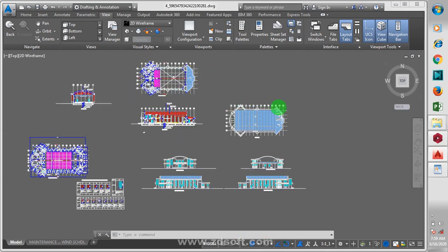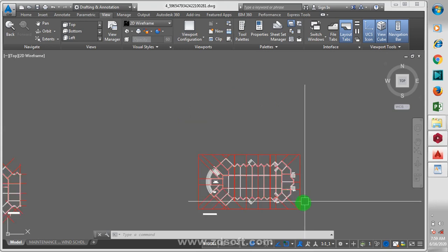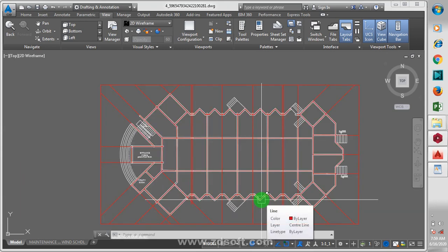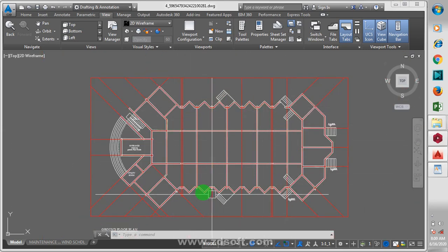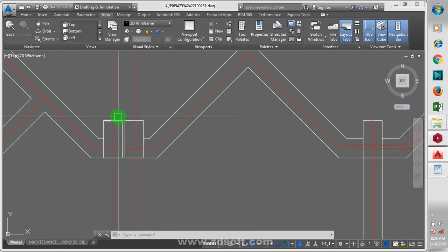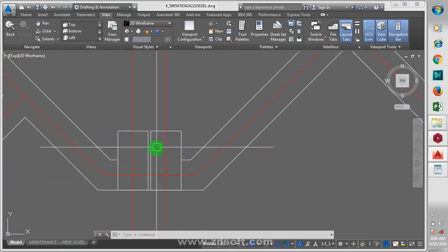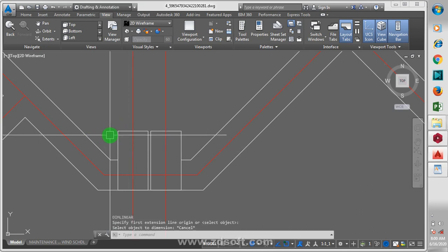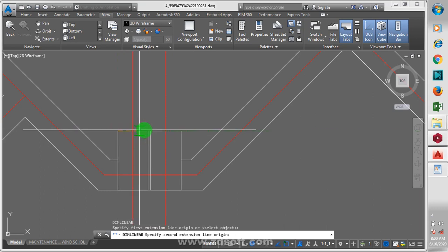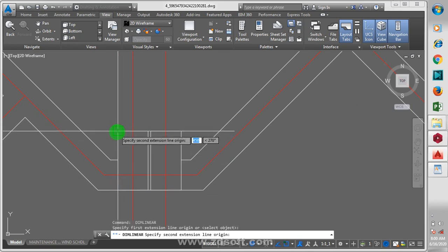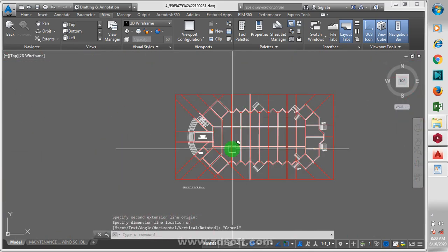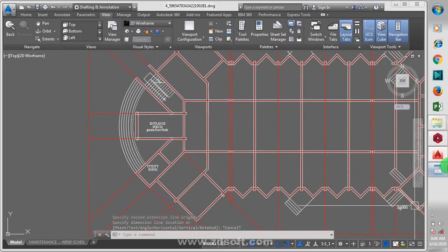As you can see here, this is from our architectural working drawing which I took you through. We were able to create our general arrangement, which is very much available on our YouTube channel. Now I'm going to maintain some of the sizes of the columns. This could be for aesthetic purpose. You can see here this is 230 by 450, so I'm going to maintain that on my design. There are so many things you put into consideration when coming up with your general arrangement. You can see this is 230, the height here is 450.